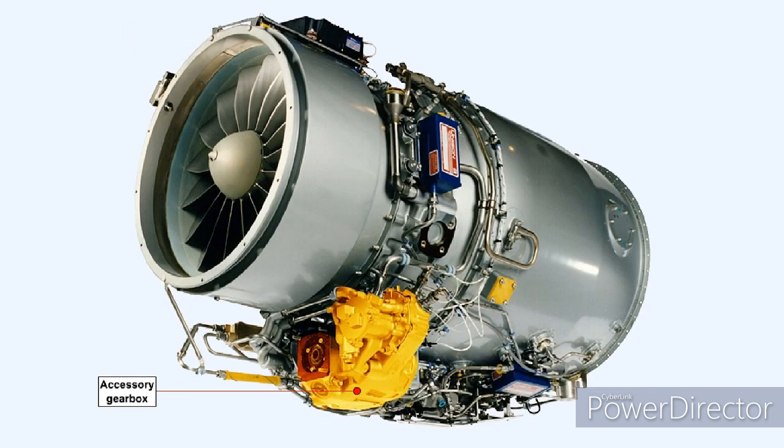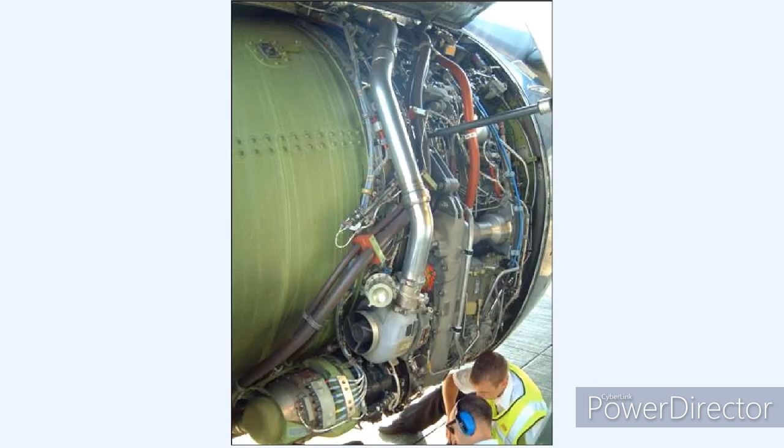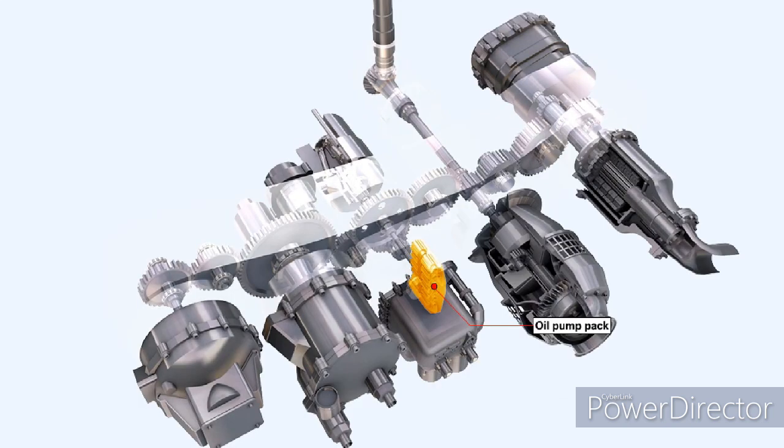Having to fit the gearbox around the engine means that the accessory gearbox must have a banana-like shape. For ease of access during servicing, the accessory gearbox is usually located on the underside of the engine. This picture shows an accessory gearbox and some of the associated accessories. Worthy of interest are the oil pumps, which are contained in an oil pump pack, a unit which contains one pressure pump and a number of scavenge pumps. In some engines, as many as 6 scavenge pumps may be contained in an oil pump pack.